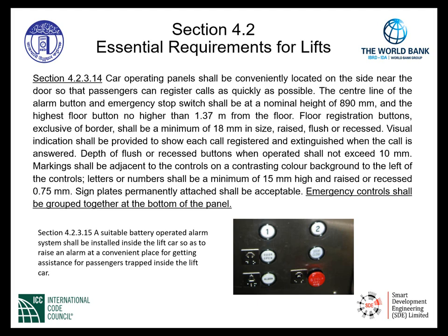Floor registration buttons, exclusive of border, shall be a minimum of 18 millimeters in size. Raised, flush, or recessed. Visual indication shall be provided to show each call registered and extinguished when the call is answered. The depth of flush or recess buttons when operated shall not exceed 10 millimeters. Markings shall be adjacent to the controls on a contrasting color background to the left of the controls. Letters or numbers shall be a minimum of 15 millimeters high and raised or recessed 0.75 millimeter. Sign plates permanently attached shall be acceptable.